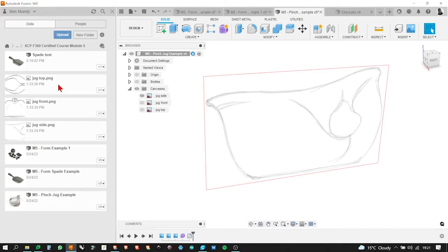So as I was developing this design, I did some sketches, and I was taught to design things in orthographic projection, but that's probably my age more than anything else. But that's what I've got, and this is probably the bare minimum of what you might need. You could just start with a side view and sort of work everything else out in your head, but it's useful to have more than one reference sketch. Ideal to have 3 or more, perhaps. But 3 is probably a good number to think about.